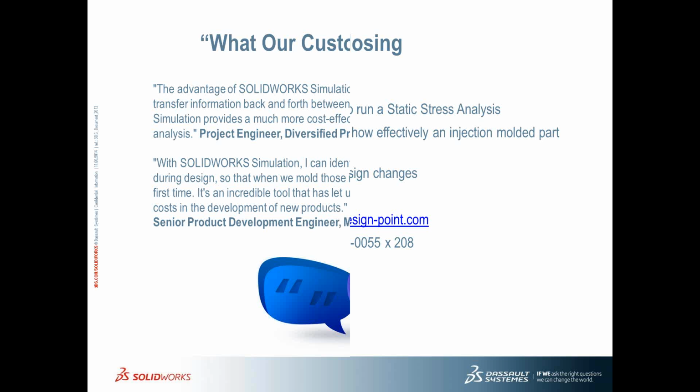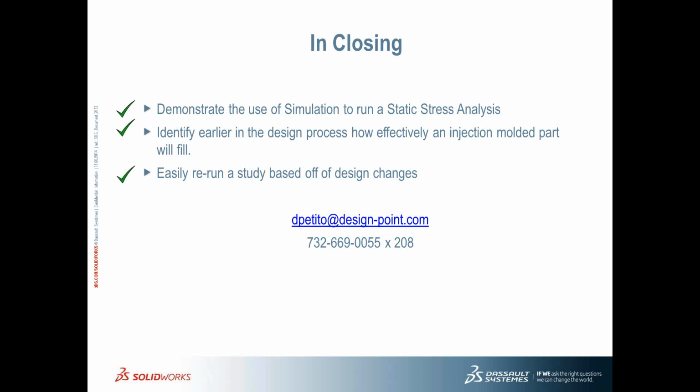So again, in closing and in summary, just to go through some things that we went through. We demonstrated the use of simulation to run a static stress analysis. Thanks so much for running through that, Matt. That was awesome. We were also able to identify earlier in the design process how effectively an injection molded part will fill. We went through required injection pressure, determining gate locations, fill times, things like that. And we thinned down some of the parts on the design, as you saw, and easily reran a study based off of design changes.